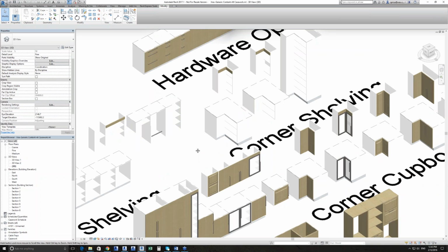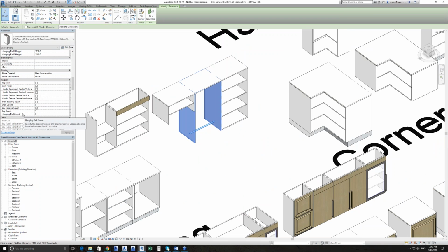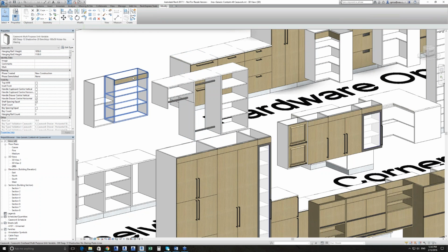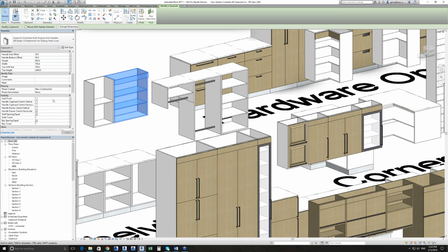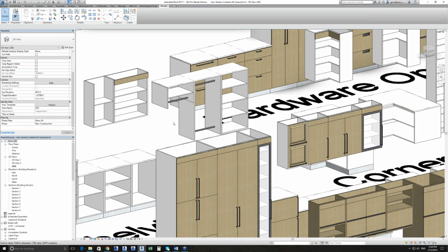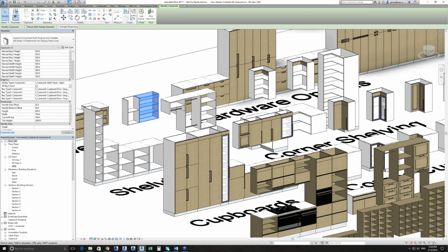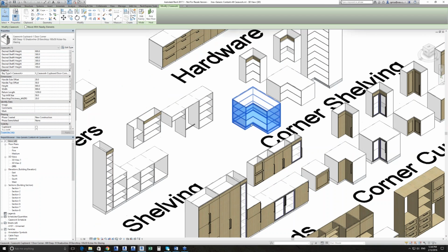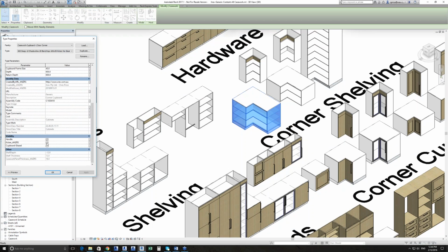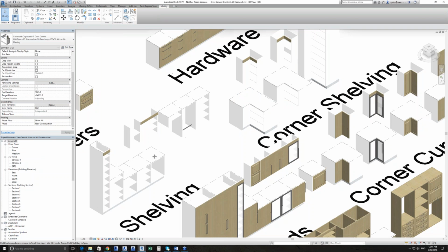You can see with these we have options for your hanging rails. This one has 2 hanging rails. You can see the other one just there. You have options for things like top infills, so it needs to fill a bit over the top. And again, all of these have full tooltips to explain all the different options. Most things in these cases are instance-based, just because for maximum flexibility, we understand what you're needing to do there. Corner options, and then at your type parameters, you just have things like the kicker size, the depth of the actual panel, the carcasses, and cupboard frame sizes if it's a glazed cupboard, for example, and whether or not it's got a kicker or a handle. So there's all sorts of combinations you can do.